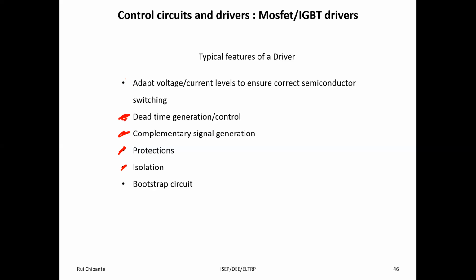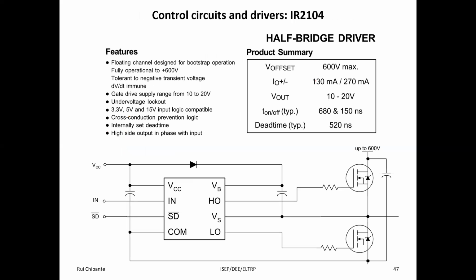We can also use drivers to adapt levels of voltage and current, okay, because I can have at the input of the driver a signal that can vary between, let's say, 0 and 5 volt, okay.